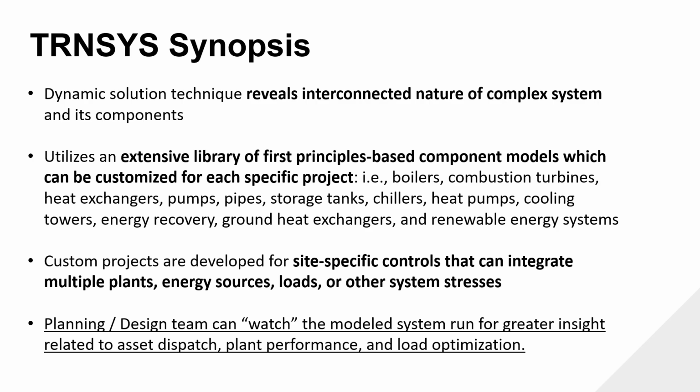So again, it's really putting together an interconnected, complex system and all of its components, and you write control sequences to get it to operate, just as you would if you had a building and a BMS, and you've got to write code to get it to operate. And the nice thing about this digital twin is that, similar to Modelica, you can output that exact same operation sequence, put it in the plan and spec, and now the building operator has exactly the code to write to operate the system how it did in the model.